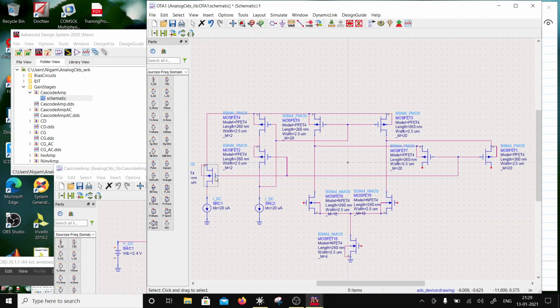So these are going to be NMOSes. So I'm going to take one NMOS. So let's take that NMOS over here, correct? And then basically I want to draw current out of this, right? So I'll take 2 NMOSes. This is called improving the slew rate of the OTA, because these are going to provide you more currents into the 2 legs. Okay, so here it goes like that.